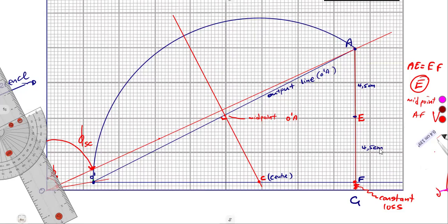So maybe yours is 4.6, maybe yours is 5. You work with the measurement that you are taking. The comment section is also there, so let's communicate and see the values that you are getting. With point E, it is midway because we are told the rotor copper loss is equal to the stator copper loss. That is why E is in between. If it is not like that, you must have the proper way of finding E. We are going to do that with a specific question.